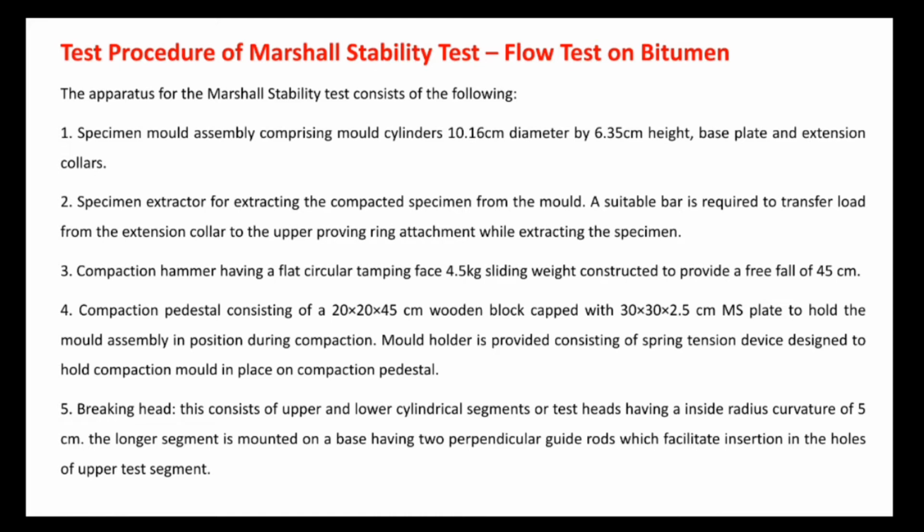The stability value of the bituminous mix is the maximum load in kg before the specimen fails, whereas the flow value is the corresponding deformation.